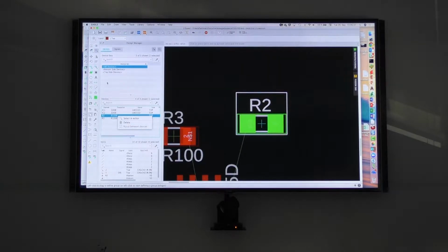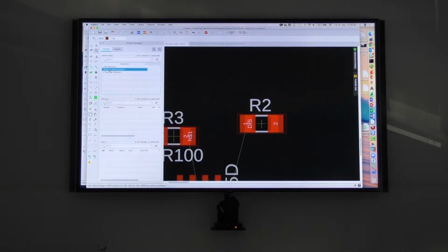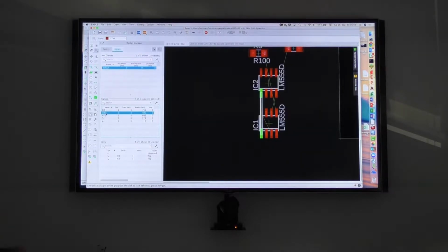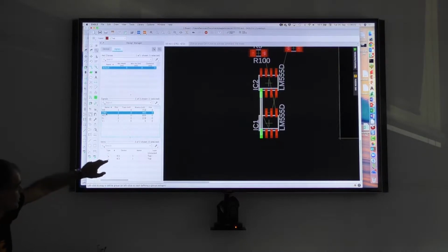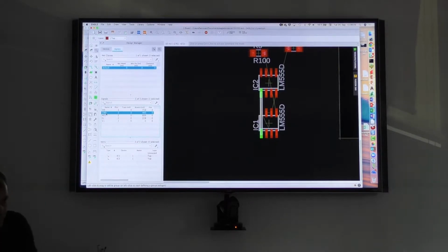You can decide on what's on the bottom side, what's on the top side, so I see it in the list, for example. And there we have the signals as well. That's not much, but you see at the moment we have different signals in the board. If I click on one of these, okay, I can see it, and I see also what belongs to the signal. There's which components are connected, are there traces, are there layers and so on.